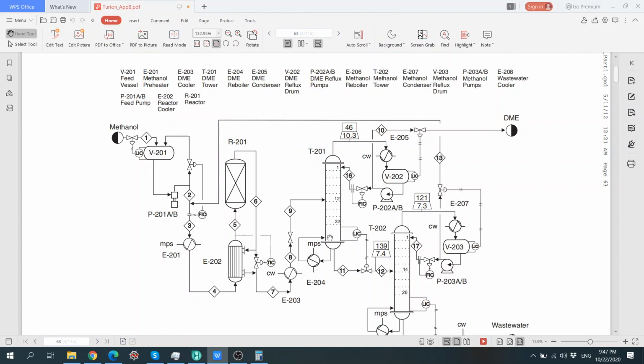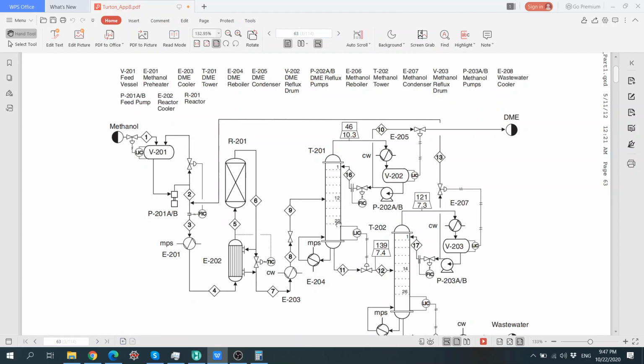This liquid is going down over here, that liquid is going down over there. So we have two different concentrations of liquid, but they are collected in the same part of the column. Hence, we don't consider this as a separation unit. So we only consider tray 1 until tray 22 as the separation unit.